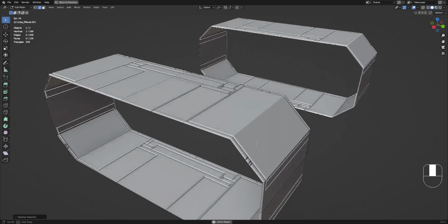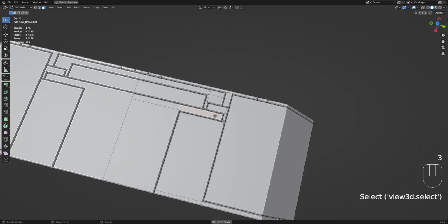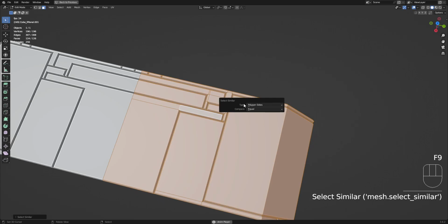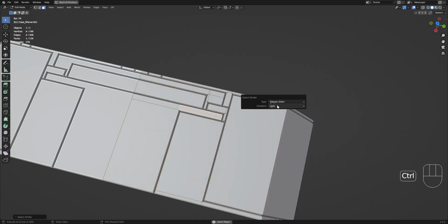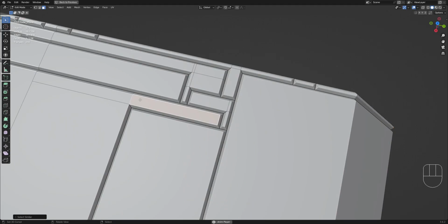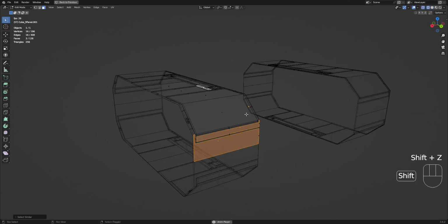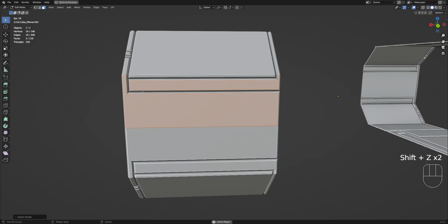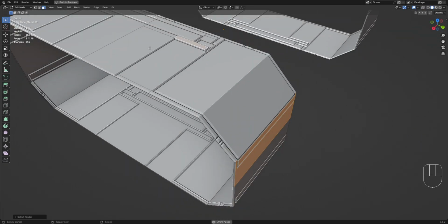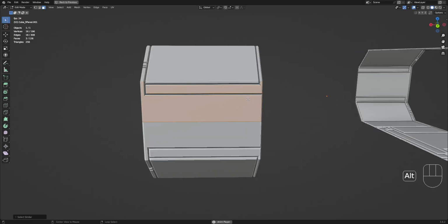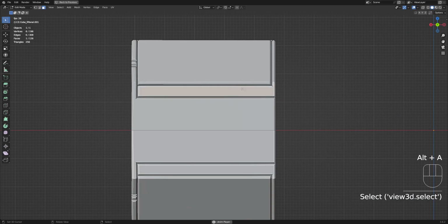we can check for ngons using select a face, then Shift G, and then polygon size F9, and more than or greater than from the selection. So greater than 4 edges, and there we go. We have this one, which is a different plane from what we're working on here. So let's start working on this plane.